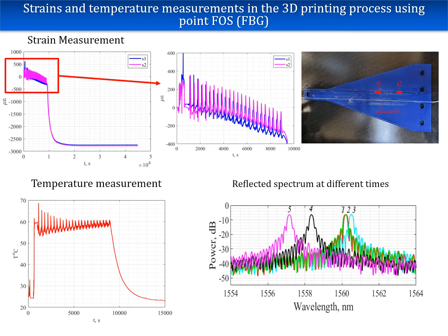In the process of manufacturing samples, the readings of the sensors were recorded. On the slide, the graph of strain changes is given, taking into account temperature compensation, measured by the point sensor. The whole history of the printing process itself and the time period after printing is presented. It should be noted that the main process of formation of technological strains begins after the end of the printing process, during the cooling of the sample, and reaches an asymptotic value 5.5 hours after the sensor embedment.